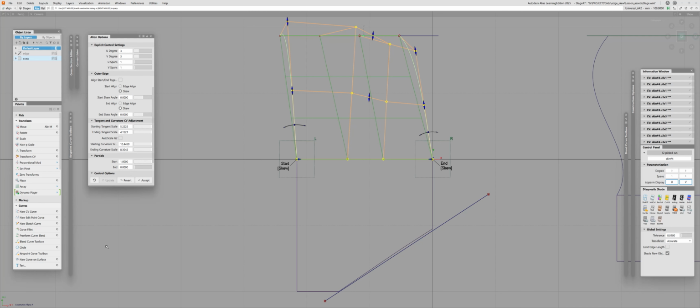On top of that, it doesn't matter how you trim. You trim it like this, you make a hole, you make it an arc, the result will be literally the same, one-to-one. So it reparameterizes it in a different way, and the actual trim is not really in effect. The moment you trim it, it's all gone. So now the skewing angle is not matching the original angle of the surface. Now, what are you going to do with this? How to solve this situation?